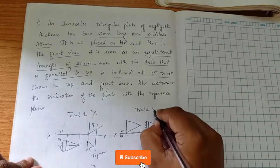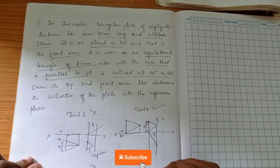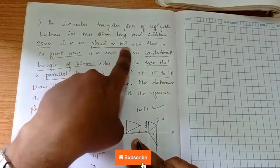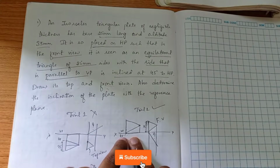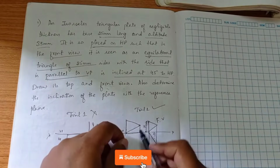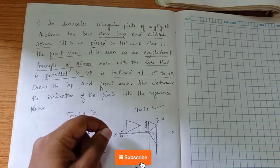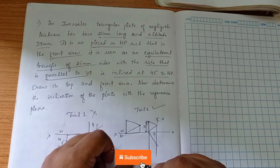So this trial 2 is correct, because you can see this is an equilateral triangle, so we are getting it in the front view. Both the conditions we have to match. So it is placed on HP such that in the front view we are placing an isosceles triangle in such a way that it is touching the HP plane. How is it touching the HP plane? By placing on the XY line, we are making one of the corners touch the HP. So when it is inclined in the second position, it is seen as an equilateral triangle of dimension 25.